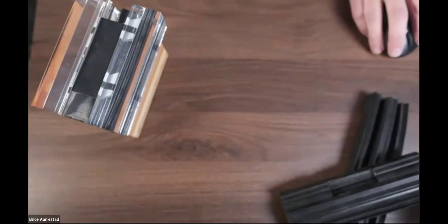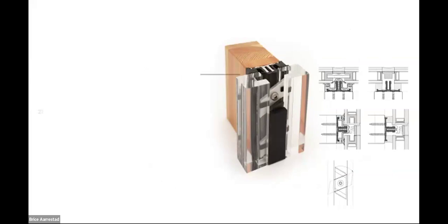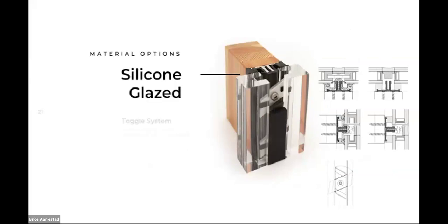There are a couple different ways that we can also finish it. Besides the conventional cap system, we can also do it as a silicone glazed system. There are a couple different approaches to this, using a toggle or using conventional silicone glazed components. So the details there, you're seeing a toggle that is